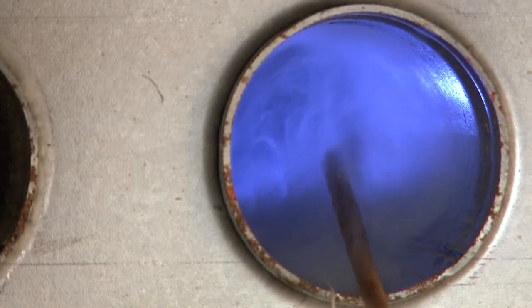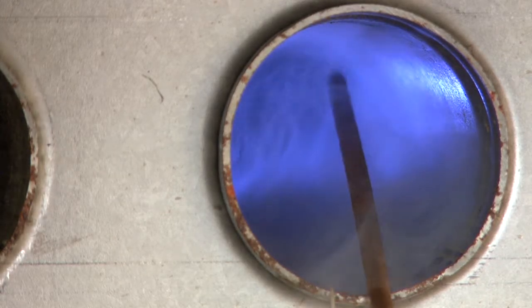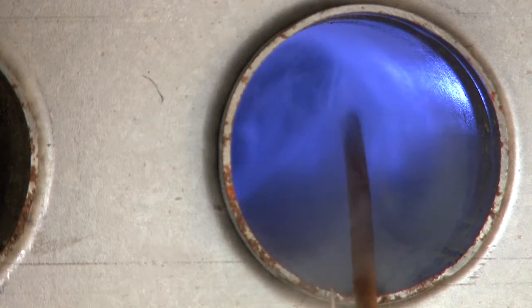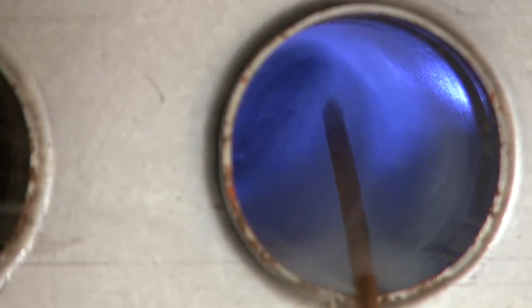I do want to point out, even though this video is more for a breach in the heat exchanger, the other test you could do with this is if you think you've got a restriction in the heat exchanger, which is really rare. If you've got just one burner rolling out and you do a smoke test and you don't see any impingement, well, maybe we've got something blocking the flow through that heat exchanger.